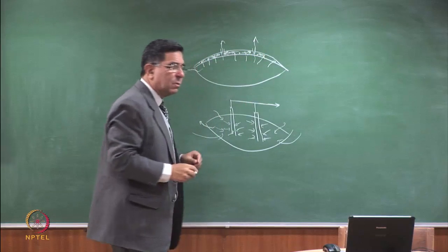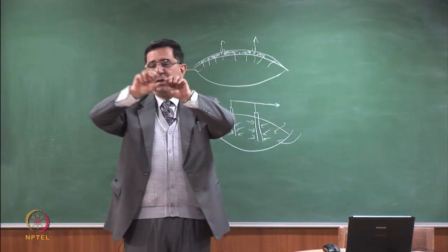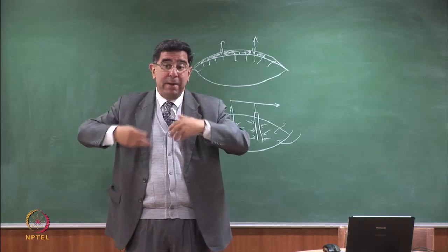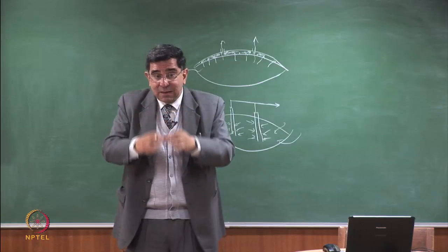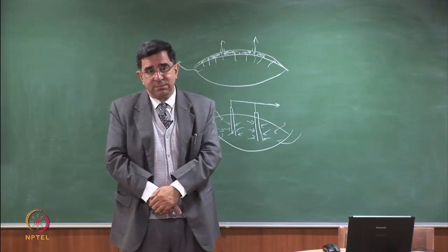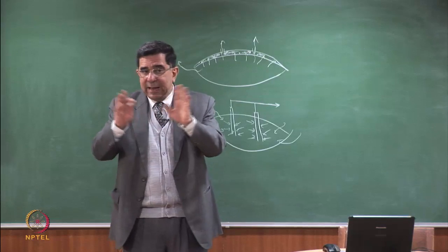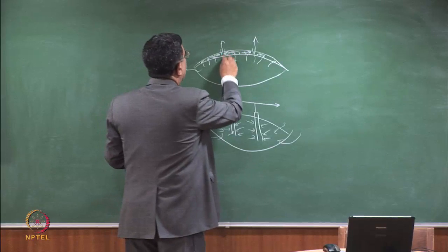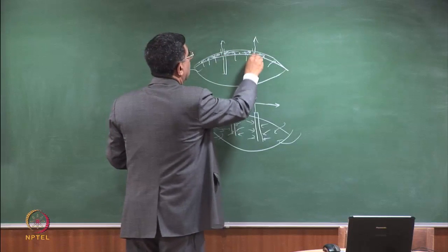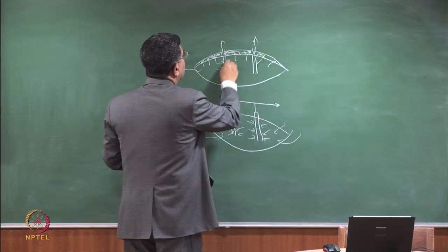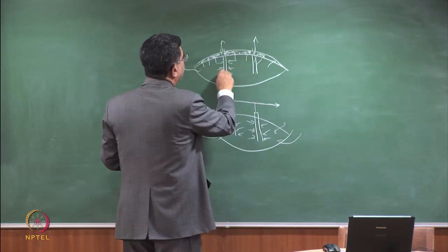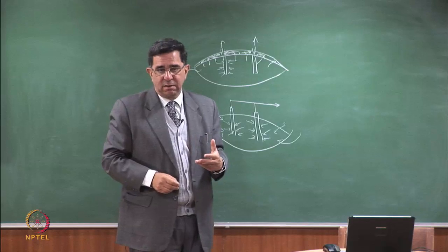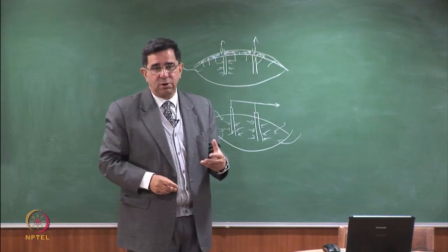So a good passive system is one which has a gravel blanket at the top. You want an even better passive system, you can make wells and fill them up with gravel. But you are not applying any suction, so it is still passive. Under self pressure, it goes to a closer drainage path. The moment you start extracting, that's the time you have got into an active system.